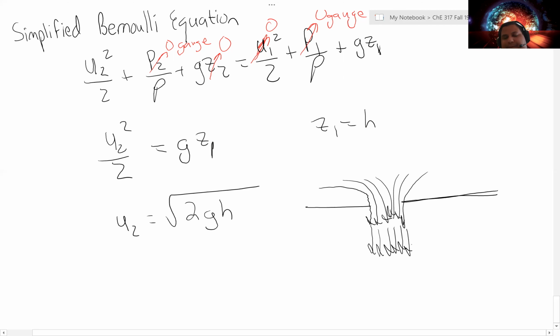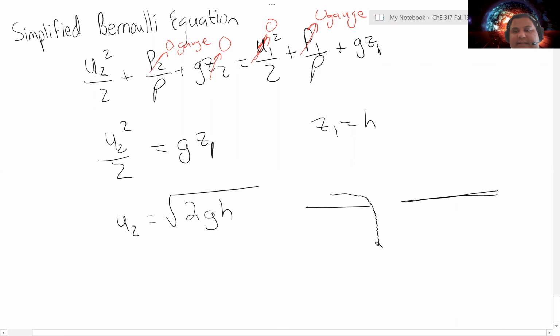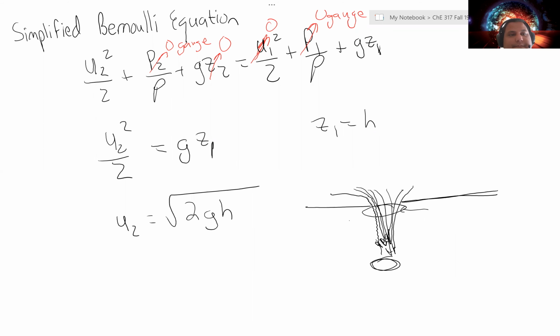However, the fluid momentum as it leaves the tank, depending on the geometry, is often such that the actual area for discharge, which we can define like this, ends up smaller than the actual cross-sectional area of the outlet.